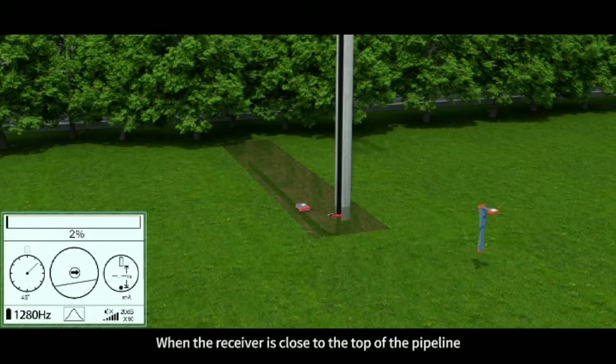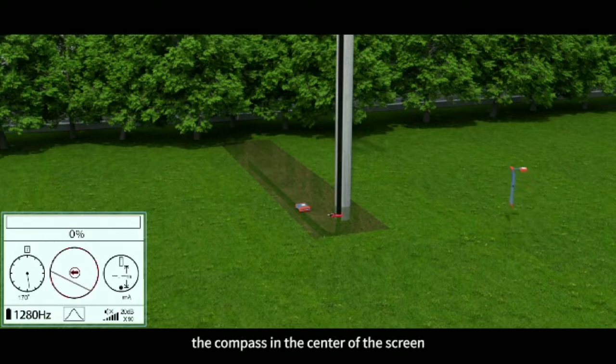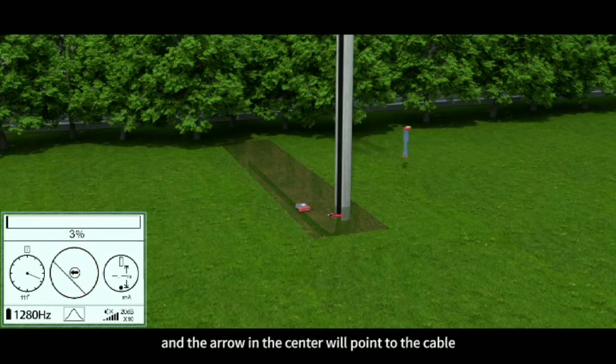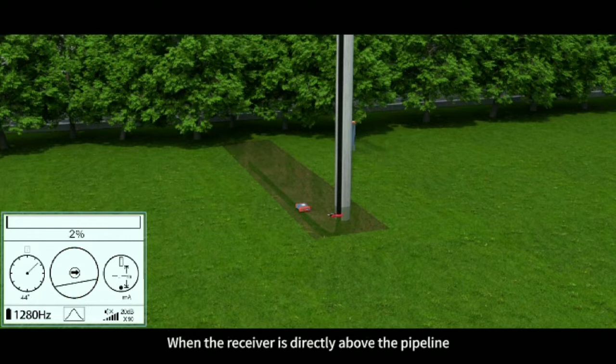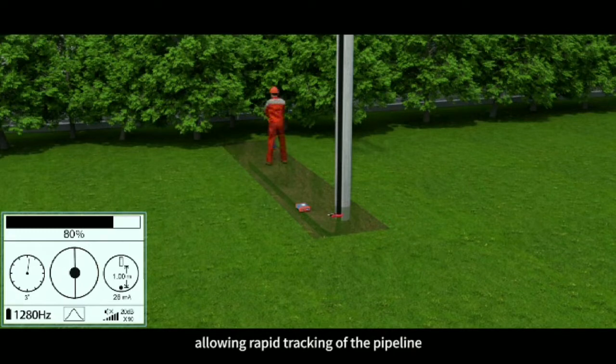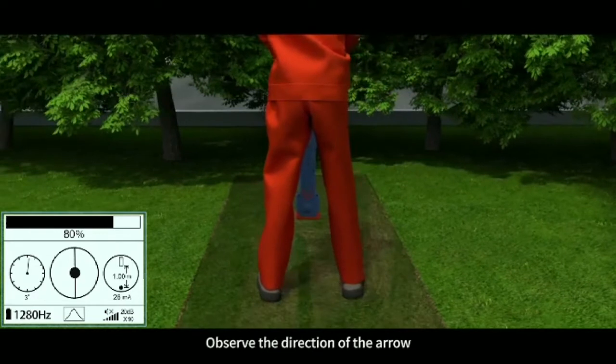When the receiver is close to the top of the pipeline, the compass in the center of the screen can visually display the position of the pipeline below the receiver, and the arrow in the center will point to the cable. When the receiver is directly above the pipeline, the arrow changes to a dot, allowing rapid checking of the pipeline. Observe the direction of the arrow.